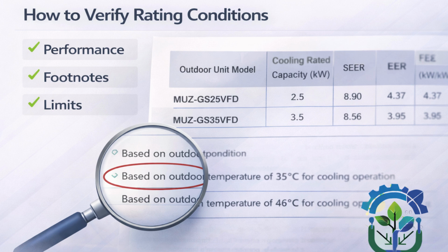And the third thing you need to check, which will be present in the compliant document, is compressor operating envelopes, which will cover high ambient. This means you actually will get 1.5 ton in the UAE summer or Middle East summer. The system will run stable, energy use is predictable, and equipment will last its design life.